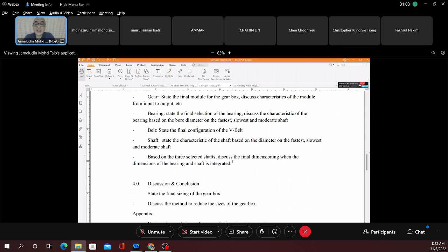In real life you have so many types of bearing, meaning that we can choose not just 3. Within the 3 there are so many classes, right? Then you have more selection than what you have now. Because of that, maybe the answer is a bit ridiculous in this case. For the bearing and the shaft, maybe you have to make a very large bearing and a very large shaft bore diameter, because of the limited size. Not to worry.